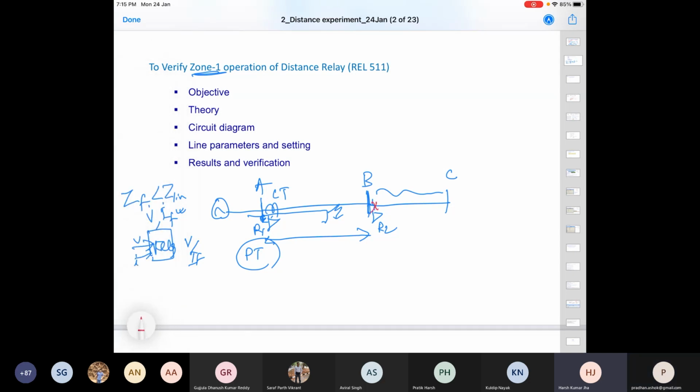Now what will happen? The relay at R1 finds the corresponding current to this. But the fault, consider this F2 fault, is in the section BC, so it is not its jurisdiction. So what will happen here for this F2? This relay will see the current. This relay will also see V divided by I. But because it is very close by, it will be confused whether it is within the AB section or beyond the AB section. That is because of current and voltage measurement uncertainty, the computational process, and so many things.